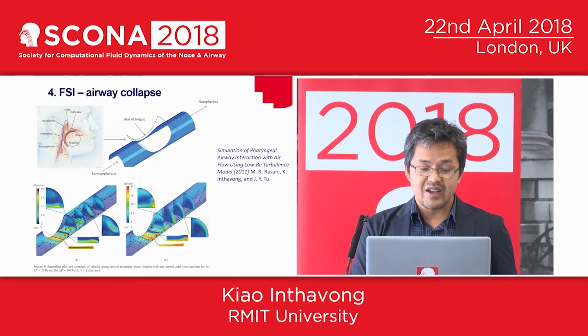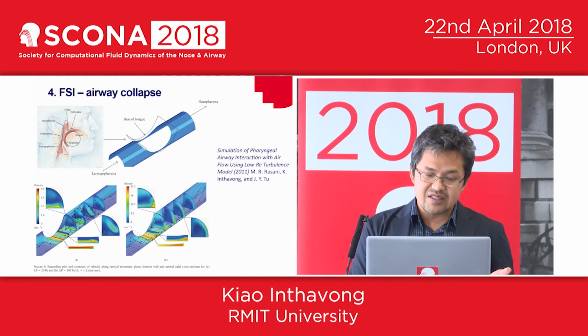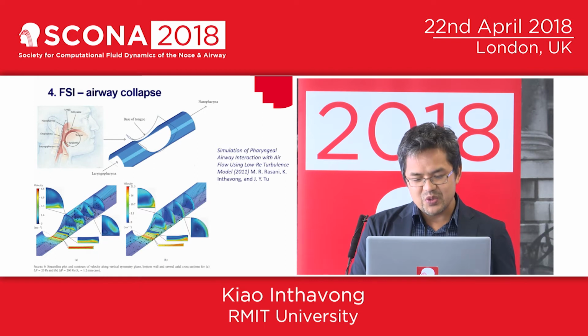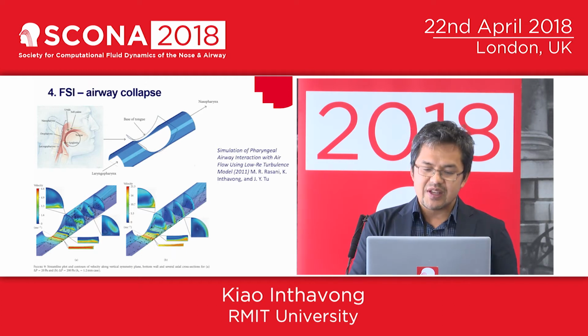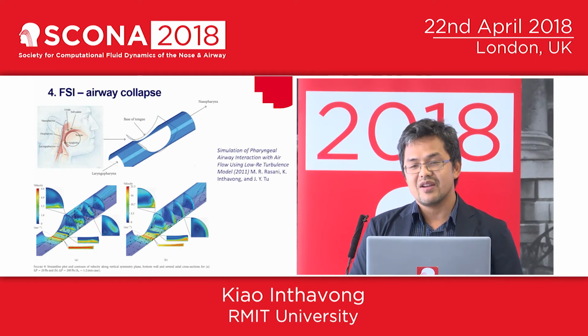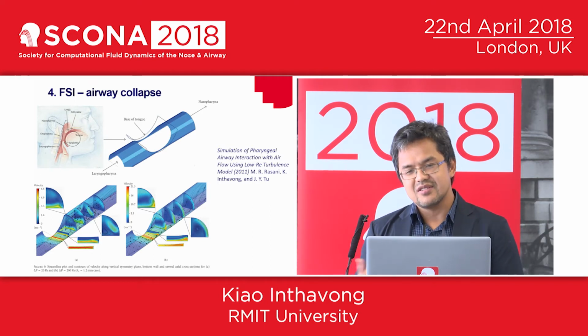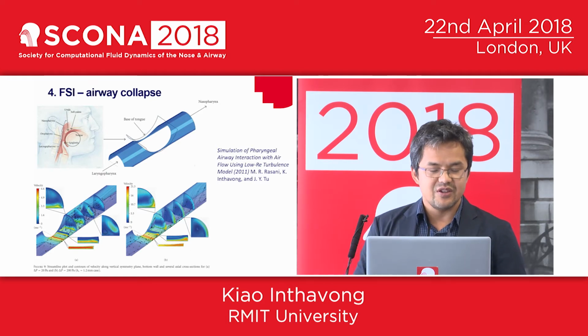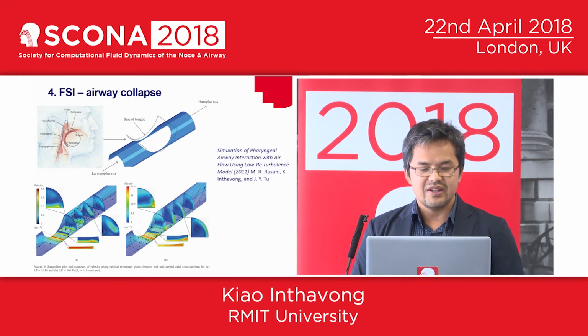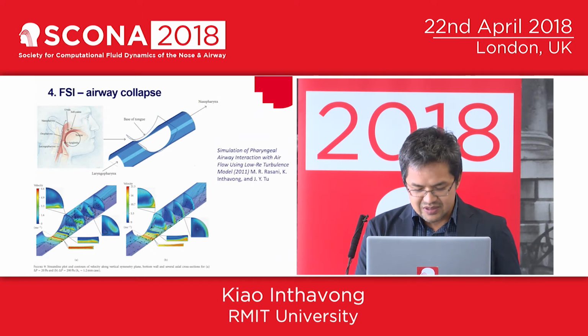Another one is FSI. FSI is quite challenging. Over three years, with a project with another student, we had a lot of trouble trying to implement it in the nasal cavity, but we looked at a simple geometry which allowed better convergence and stability, and we showed that yes, the Venturi effect and sucking down of the geometry, based on the flow rate and the flexibility of the material, can lead to different airway collapses.